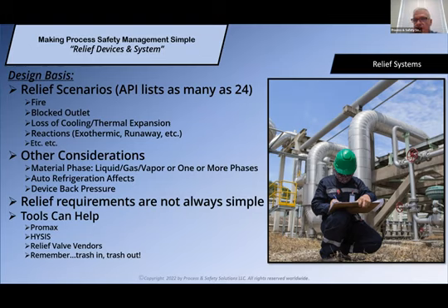What we mean by that is, if you're giving bad information in the sizing, obviously what comes out of that sizing exercise is going to be bad information as well. So making sure that all the information you gather, all of the information that goes into sizing that relief device, is current and accurate.